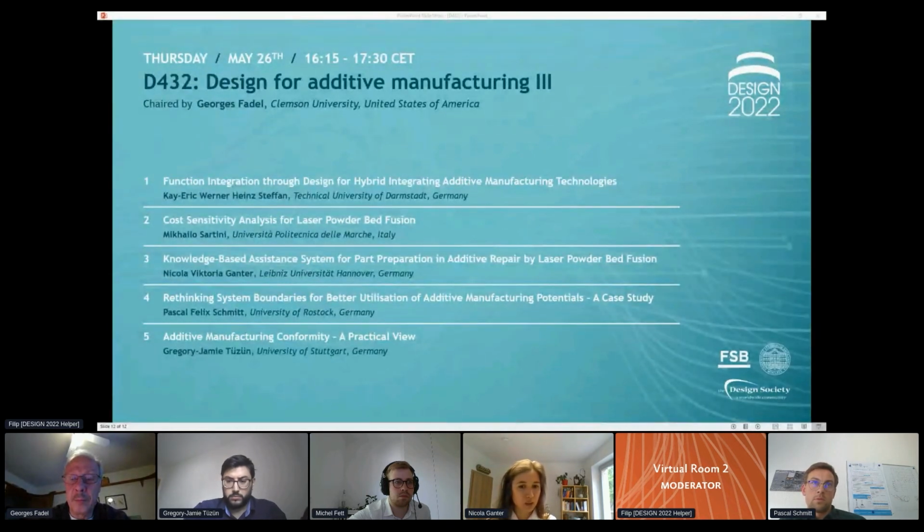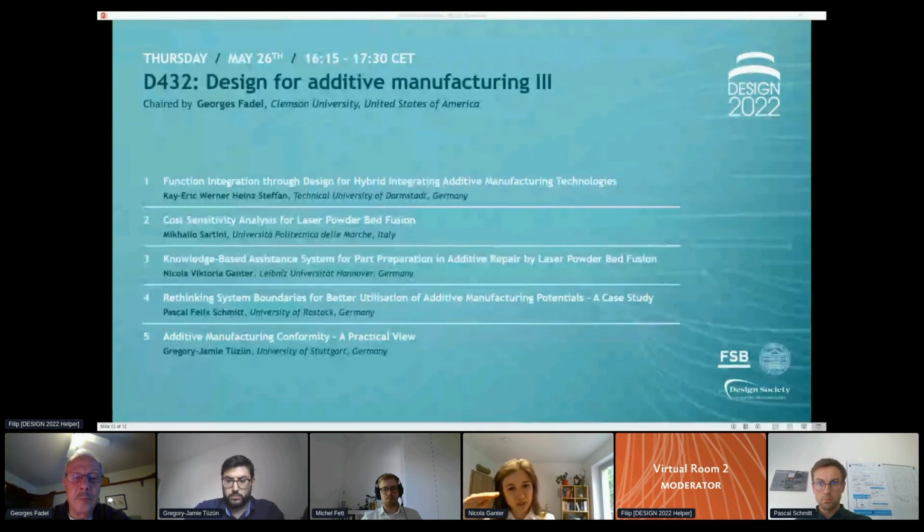But I think it would be more problematic if we would do repair cases in aluminium or in other materials where you need to heat up more. Probably there you need a machine that heats up the surface of the powder bed instead of the building platform. But we didn't look at this too much yet because we did not have the problems with the steel parts.